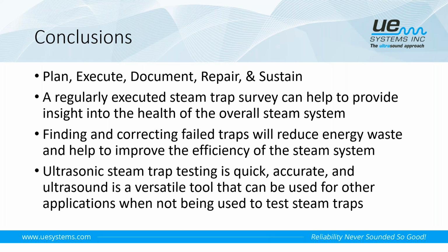I talked a little bit in the beginning and throughout about planning. So we want to make sure we have a good plan. It'll make it so much easier. And again, it's very tedious work, especially if you have thousands of steam traps in your facility. But you want to go into it with a good plan. You want to execute well. Again, whoever you're going to have doing the work, doing the survey, the ones actually testing the traps, make sure that they've been trained as to what their purpose is, what the steam traps are doing, what the steam is being used for, and then training on the ultrasound instrument.